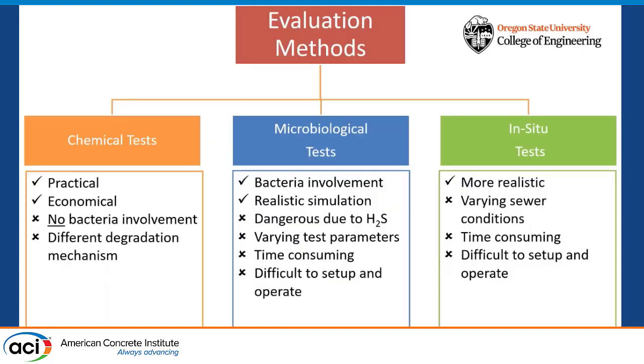So there are different evaluation methods. One is chemical tests. These tests are practical and economical, but there is no bacteria involvement in the test. So we can say these are not realistic simulations. The other option is microbiological test. There is bacteria involvement.